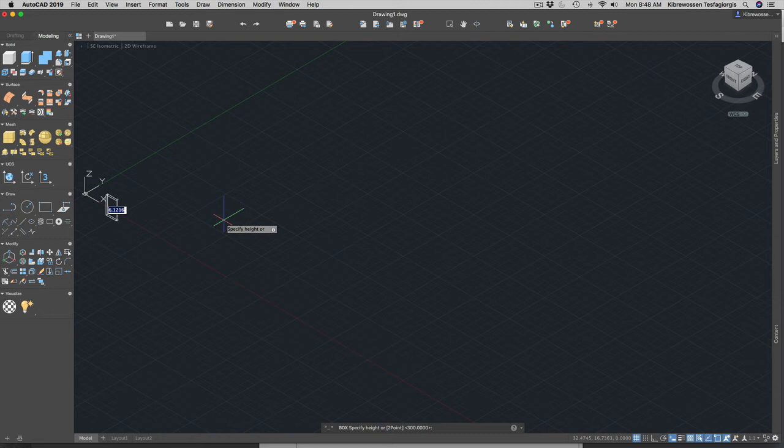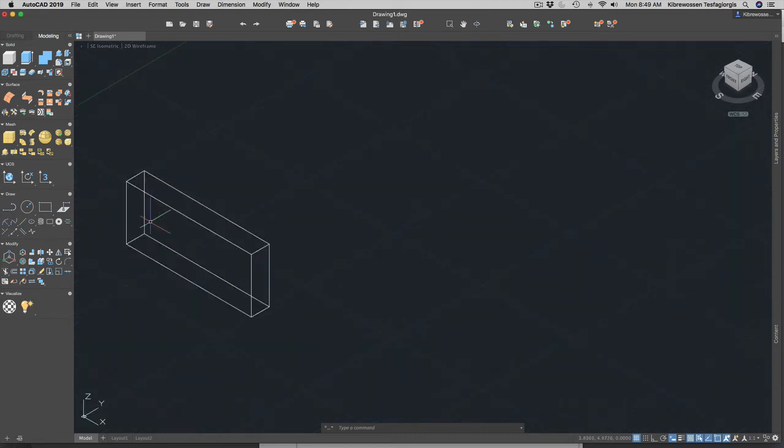But for this one, we are going to tell AutoCAD to follow the direction of the cursor, instead of entering negative values. Okay, so the height is 1.5, and I think it's to the top direction. 1.5. Otherwise we are going to change it later.